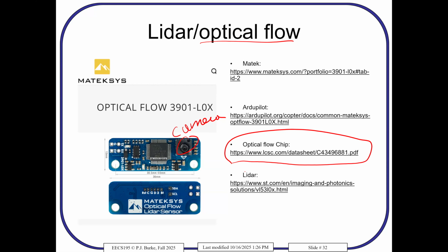And that's also on this Maytech chip, because it's pretty simple. And that's also supported by autopilot. So I'd like you to try that also. And if it works the way I hope, you'll be able to hover in the drone cage, because you'll have 1 centimeter XY control and you'll have 1 centimeter Z control. It'll be LiDAR for the Z and optical flow for the XY, and you should be able to hover in the drone cage without doing any piloting at all.